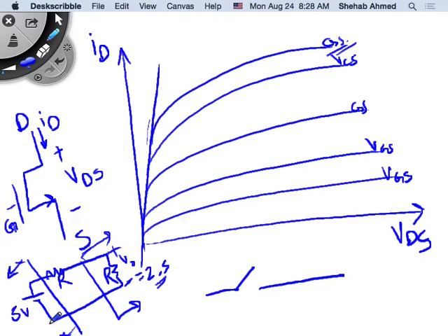I've put an amplifier in there, a box in there. This box can increase the signal's value, decrease the signal's value, change its frequency response, do whatever. That was the amplifier, right? At the end of the day, in that course, you were coming up with transfer functions to define your circuit. So you can make this transfer function look like anything you want. This is a simple transfer function where I'm just dividing the magnitude by 2, right? And you can do that very easily with this circuit, correct? Can somebody tell me how you would do this with a MOSFET, for the people that took 325?